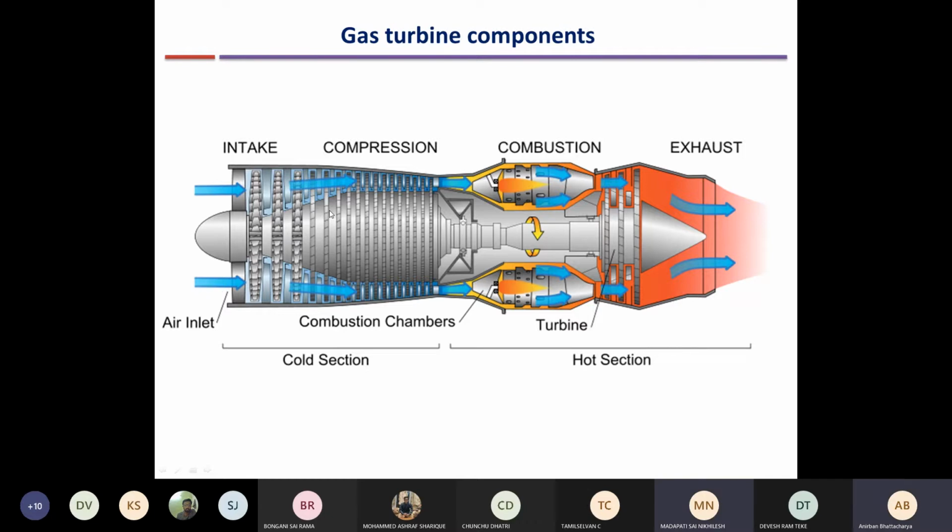Not really. What is the maximum pressure? Like what were the maximum pressures that we generally take for a thermal power plant? So what is the pressure in the boiler? You can say maximum pressure after the pumps or in the boiler. Typical pressures that we used to take are around 10 MPa, 15 MPa, 20 MPa, right? 22 MPa is the critical pressure of water. So say it is 10 MPa or 15 MPa.